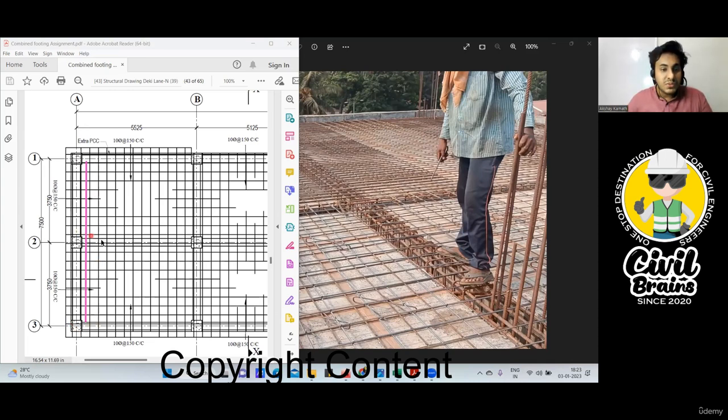But again, I mentioned this is a beam what we have here. So practically this is that beam. So this beam, you're not putting the bar. Your bar will actually end here. It will start from here. It will end from here. That's it. Okay. And then again, it will start from here. It will end from here. Just because a contractor who doesn't want to cut the bar, they will put practically straight bar. But we'll do the cutting length what is exactly required. Got it, no? So what we'll do, in 7,500 minus 150 from here, minus 150 from here, and this middle 300 width of your beam, that also will deduct. This much you understood, no?